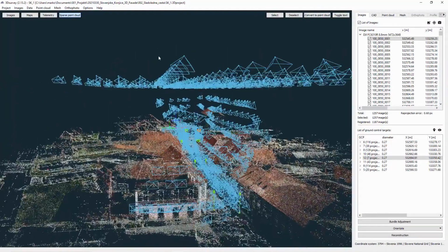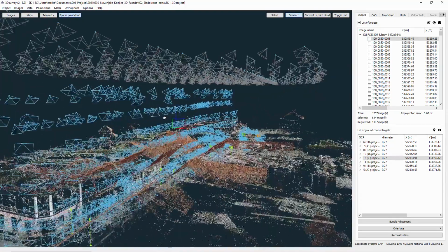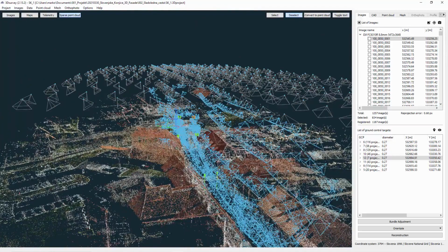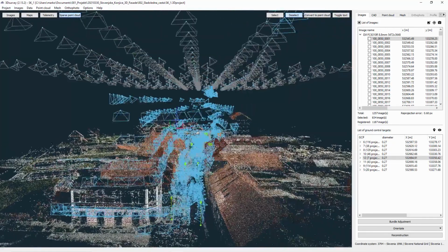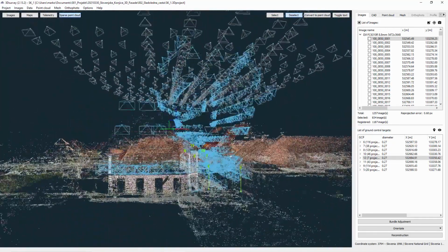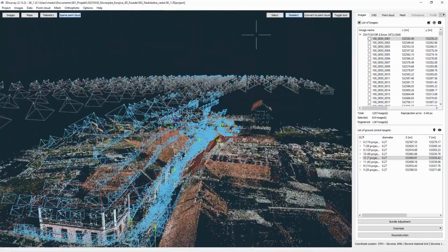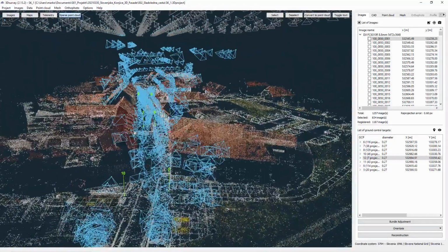So here first the double grid mission. Let's maybe deselect this one. Okay, so this was the double grid mission, and then I just go with a manual flight, flying in a row, turn the camera a bit down and trigger side images. The first double grid mission was at 35-meter height, then I go to 30 meters, 25, 20, so every 5 meters I go lower and try to take the best side images to get most of the detail out of it. The end result must be a pretty detailed, accurate 3D model with a resolution of 2 or 3 millimeters, so super accurate.